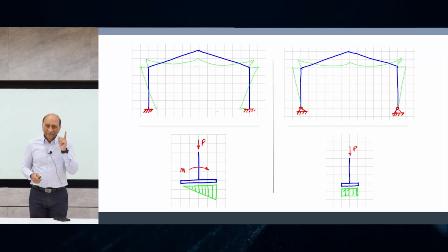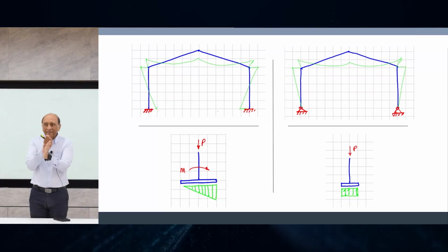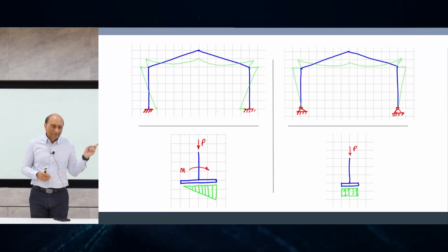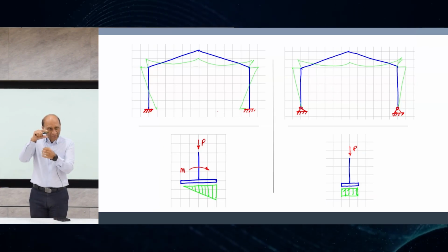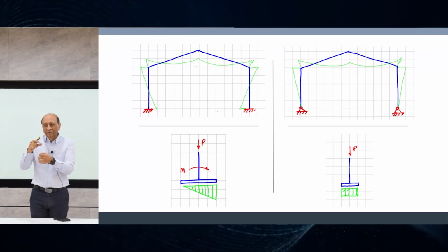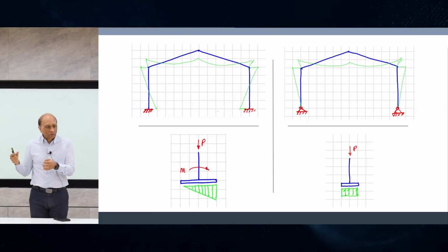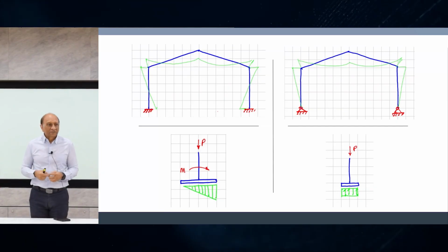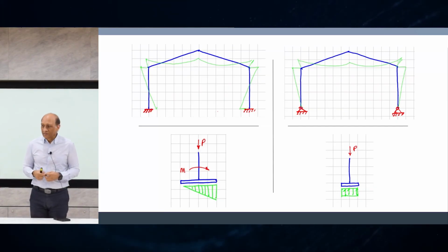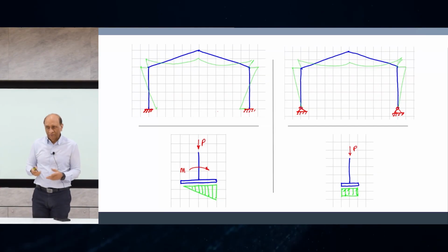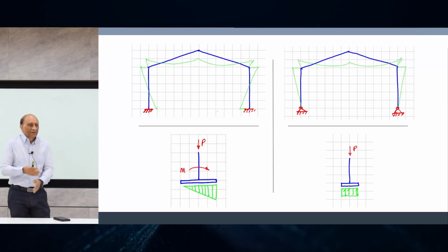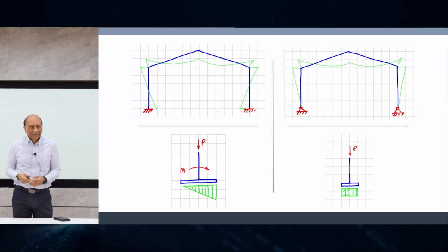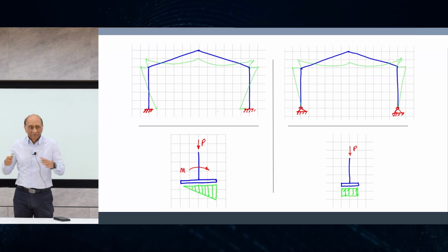So when I made the drawing, I actually designed a hinge at the base of the column. It is a concrete structure, not a steel one. So I designed a hinge connection between the footing and the column to make sure that I construct what I have assumed. And it was not usual for people to see a hinge detail in a concrete column because I brought the bars and crossed them so it will crack and create a hinge there. And people were making fun of me, saying, what are you doing? We take the column bars all the way down and you are crossing them. And this will crack. I said, yeah, exactly. I want it to crack at the base so that it will perform like a hinge.